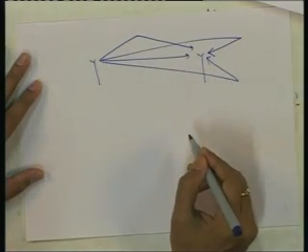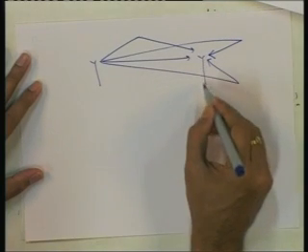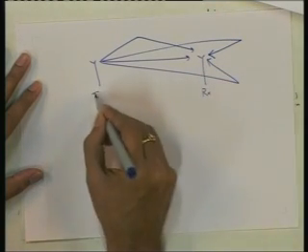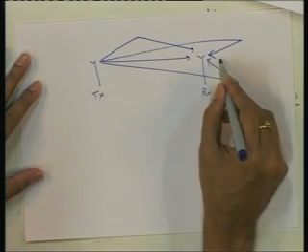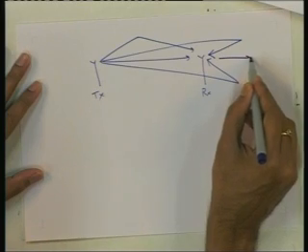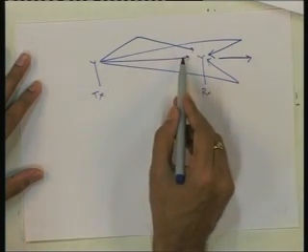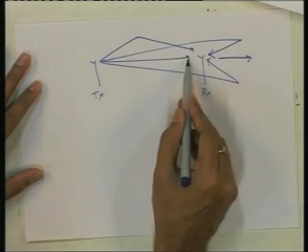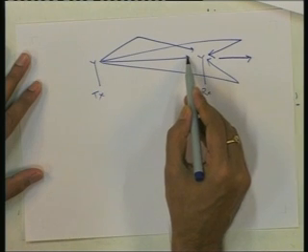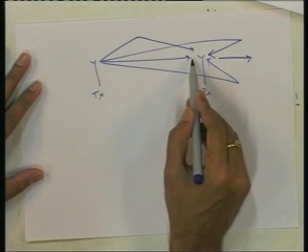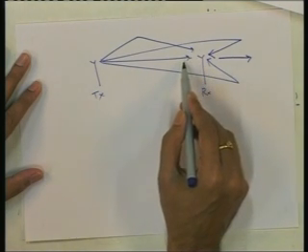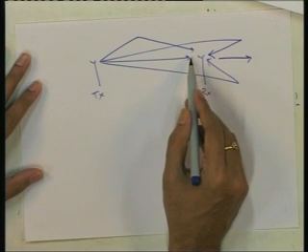Let us say there are these 4 paths, and the receiver antenna is moving in this direction. Then these path lengths are increasing. So, the signal received through these paths, the frequency of them will decrease.